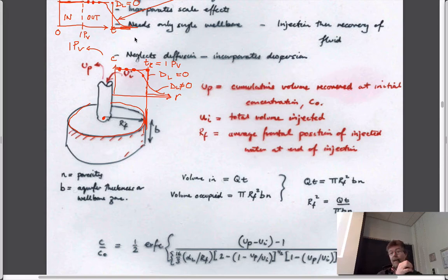And the reason for that is that the dispersion characteristics are highly sensitive to the magnitudes of the velocities that we induce. Because we're injecting fluid at some prescribed advective velocity, which is typically much higher than happens in the natural case in the field, the dispersion that we would get would be dominated by mechanical effects and it wouldn't necessarily reflect the true behaviors.